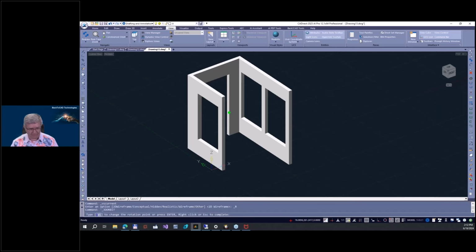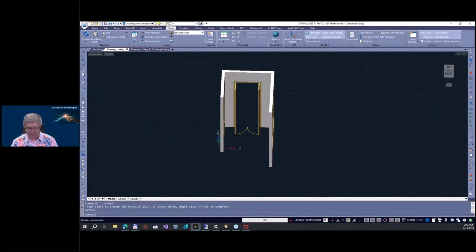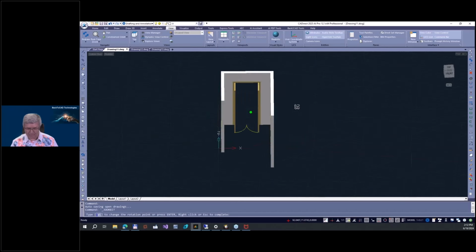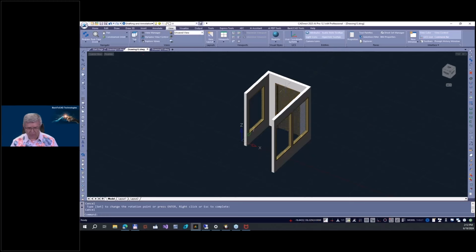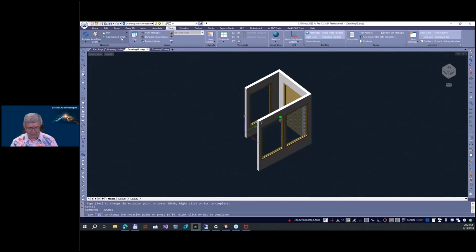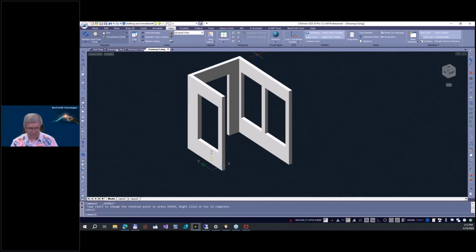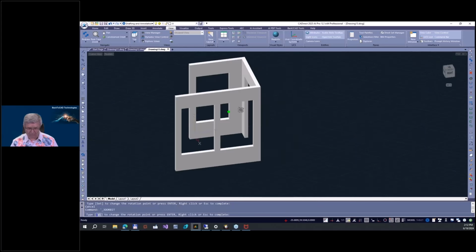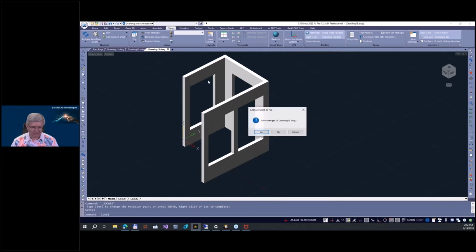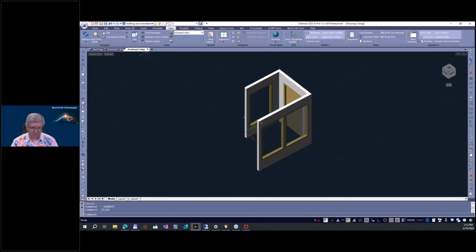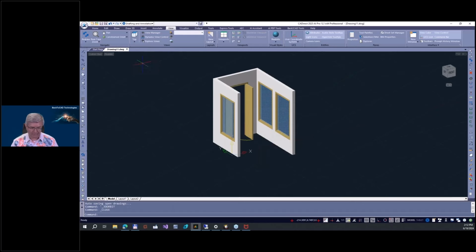Again, here it was very easy. Small drawing. You see, made using our CADirect. Then here, export and import as IFC. And here we export and import it only with the decision we need only the walls. Perfect. But this is good only for small drawings. I'll show you something. Let me start now with real big drawings, okay? And let me check what kind of trouble you can have.